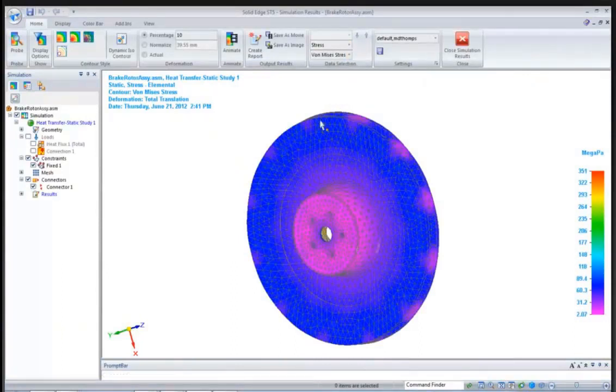So, just to finish my thought, that's radiation. And you can look up emissivity and use that if you're going to consider radiation. So the results are back here. Stress is going to be high around my constraints. We know that. We ignore that. Out here, it's very low, as it should be, because we don't have the thermal growth constrained at all, really.